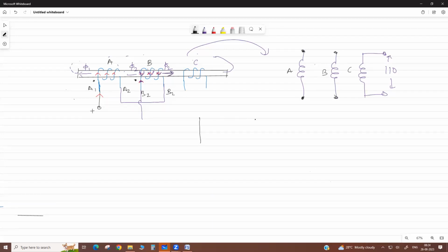On a motor, the coils are inside, but the terminals are here. By checking the continuity we can know this is coil A terminal, this is coil B, this is coil C terminal. We can find this by continuity. But we do not know whether this is A1 or A2 or vice versa. That we need to find. How can we find it?